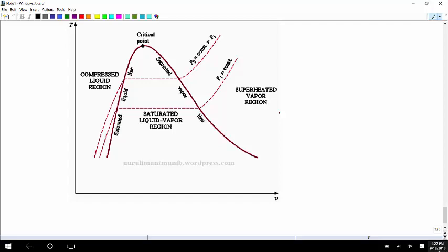And also notice that relatively, and this isn't numerically accurate, this is sort of a general picture, but notice that relatively, here versus over here, you get a pretty small change in the specific volume when you increase the temperature. Okay, so what that's saying is if you took a cup of water, measured it, put it in the pan, started heating up the water, before it gets to the boiling temperature, if you poured it back into the measuring cup, it would still be about a cup. The volume doesn't change very much.